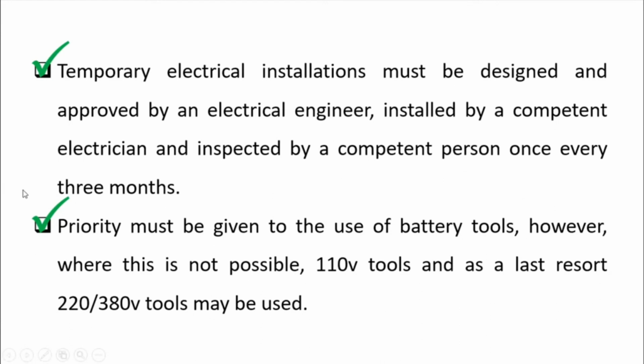So we are prioritizing the use of low voltage, such as battery tools, 12 volts, 14 volts, and if that is not possible, the last resort for power tools is 220 or 380 volts. But usually at site we are using 110 volts only, and the use of 220 and 380 volts is by permit system only.